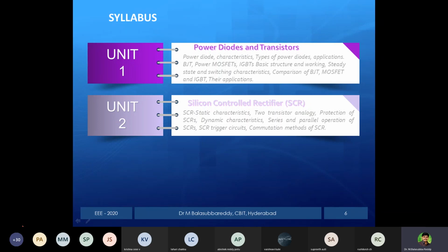Two or more alternators are connected in parallel. In substations also you can see that alternators are running. If the demand is less, they will shut down one of the alternators. If demand is more, they may add one of the alternators, in the general case. So you are synchronizing the alternators. It depends on our demand; we are able to use that parallel operation.